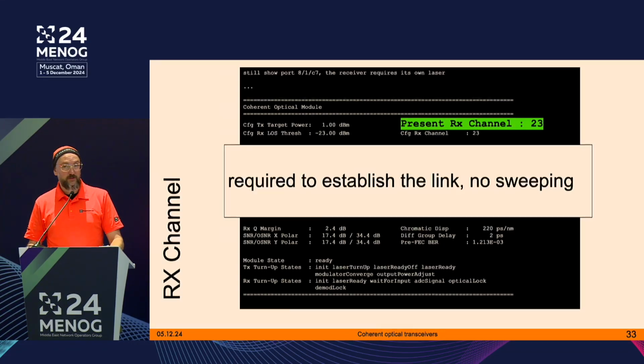And why is this important? You can build single fiber transmission with that, or spans. So the TX is, for example, on channel 25, and the RX is on channel 23, and you can transmit on one single fiber then. That's doable. But again, you need to be precise. You need to look in the specs of the transceiver itself. The maturity differs: they can tune the RX side, but not to a different channel than the TX side. And that's just due to how the physics are built inside of the transceiver. We need a local oscillator for the base frequency, and that's typically split between the TX and RX, and then we stick to the same channel.